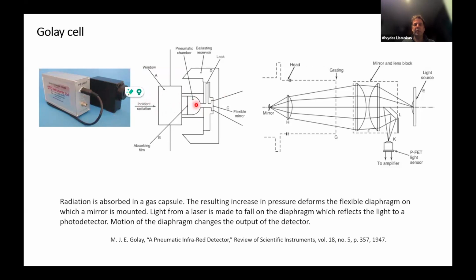If you expose it to too strong a temperature variation, mostly the absorbing film can break, and that damages the device. So it doesn't matter if you switch it on or off, you cannot protect it that way. You have to protect it against too big a thermal load.